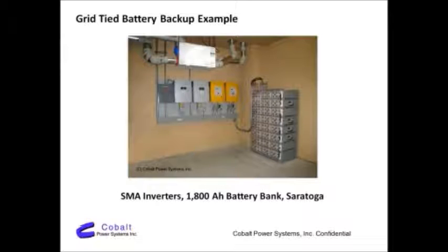Okay, so far I've talked about what's called a grid-tied photovoltaic system that does not have batteries. That's about 90% of what we do, and probably 95 to 98% of the PV systems out there nationwide and in California. The only thing it won't do for you is, when the grid goes down, a PV system has to shut off. The reason is they don't want you putting power out on the grid and endangering people who are working to correct the outage. It's a UL regulation, UL 1741, that the inverter has to shut off.